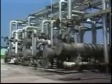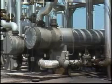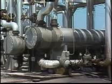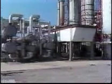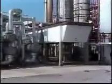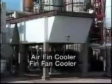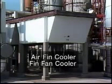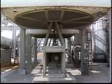increases. In a typical heat exchanger, heat is transferred by conduction, convection, and radiation from one fluid to another. As a general rule, most heat transfer occurs by conduction and convection. To get a better understanding of how heat transfer occurs in a heat exchanger, we'll use this heat exchanger. It's called an air fin cooler, or a fin fan cooler. It's used to transfer heat from a process fluid to the air that flows through the cooler. The cooler consists of a series of tubes, each of which has thin metal fins. The heat exchanger also has a fan.